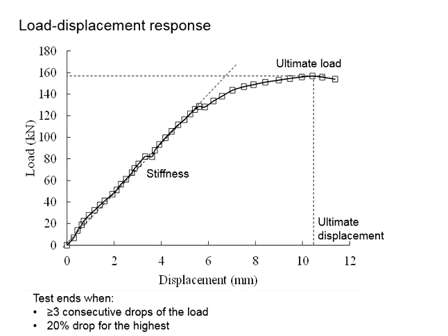If you want to know for sure, you can have more plots and observe whether the strength can go higher than that. Some may choose to go for a more conservative method, seeking a 20% drop from the highest point. By the time the load capacity has reduced 20% from the highest strength, it is nearly definite that the specimen has failed.